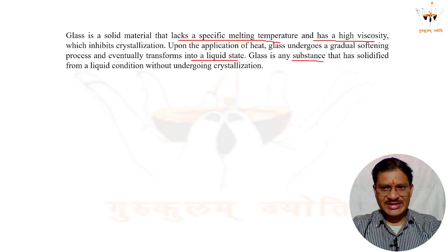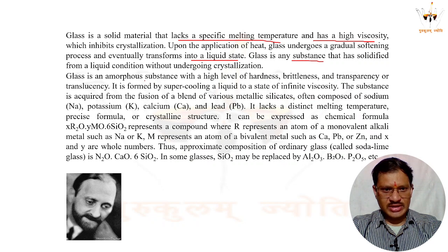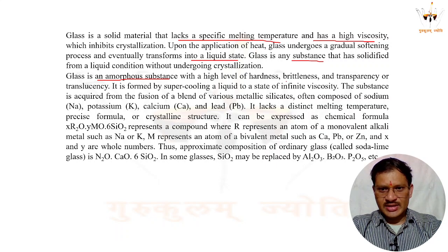Glass is any substance that has solidified from a liquid condition without undergoing crystallization. Glass is an amorphous substance with a high level of hardness, brittleness, and transparency or translucency. It is formed by supercooling a liquid to a state of infinite viscosity. The substance is obtained from a fusion of a blend of various metallic silicates, often composed of sodium, potassium, calcium, and lead. It lacks a distinct melting temperature.